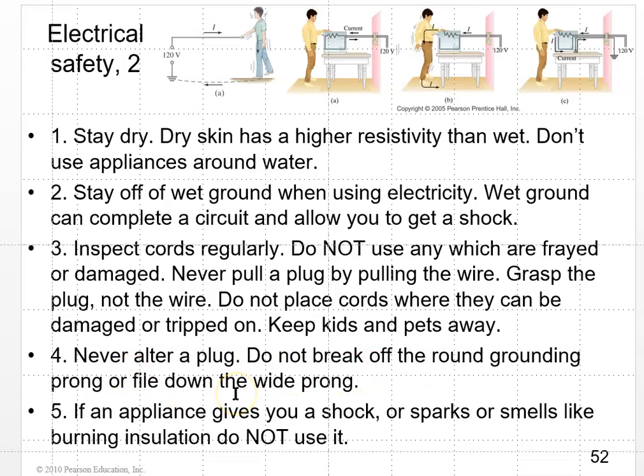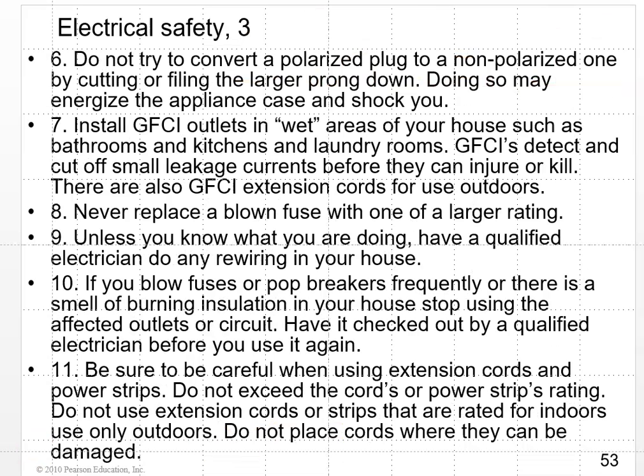Never alter a plug. Do not break off the round grounding prong or file down the wide prong. If an appliance gives you a shock or sparks or smells like burning insulation, stop using it. It's not worth having a fire. Do not try to convert a polarized plug to a non-polarized one by cutting or filing down the longer prong. Doing so might energize the appliance and shock you.